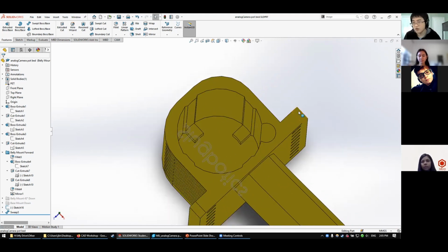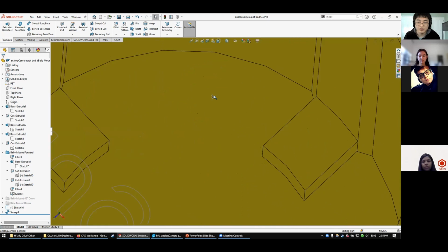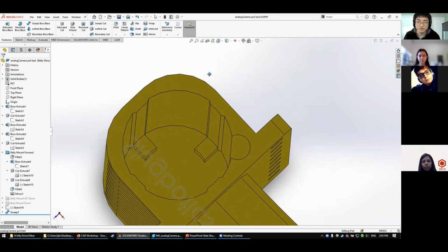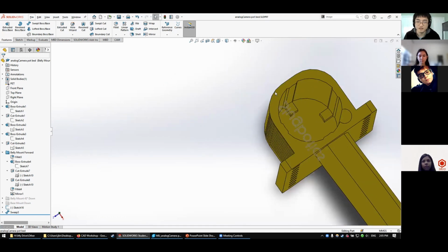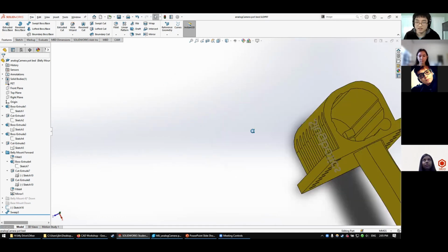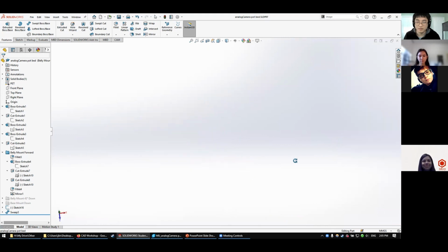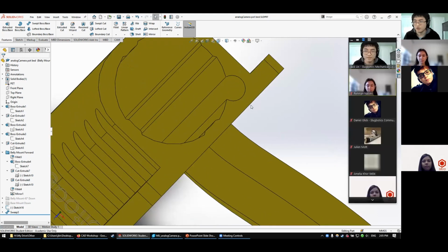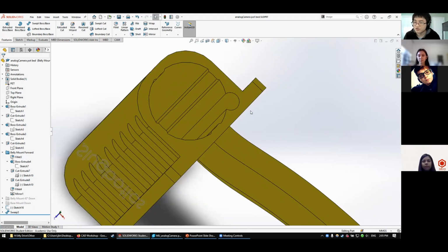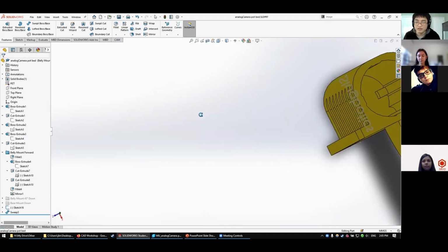And then just to show off some other modifier keys, holding Shift and middle mouse zooms in and out at the point. And Control pans around, useful tool right here. And Alt rolls the camera. Oops, did I press Alt? I am rolling somewhere really odd. But yeah, it is rolling the camera around an axis. So having these modifier keys at hand, Control, Shift, and Alt lets you do some stuff really nicely.